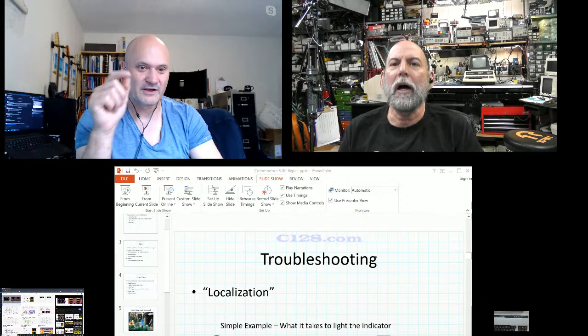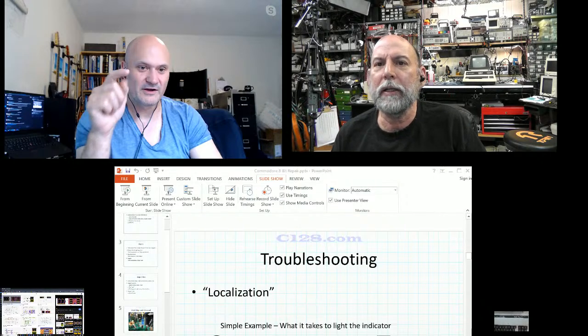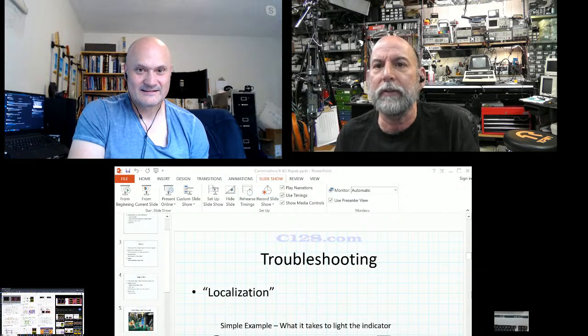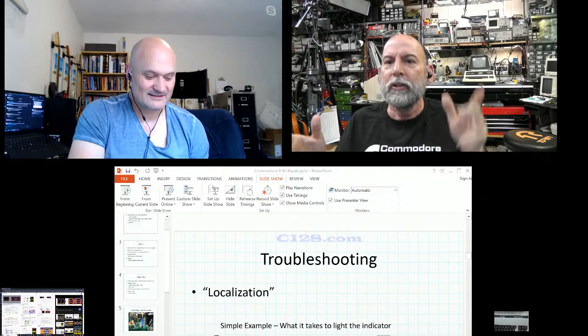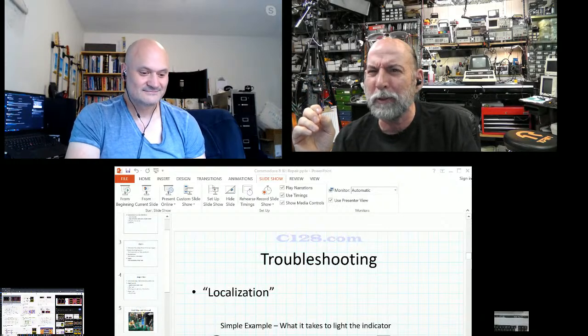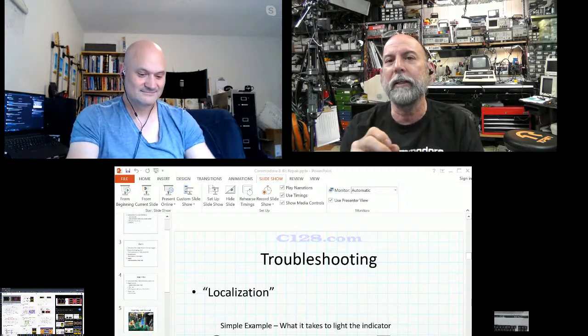So, Ben mentioned audio troubleshooting, and one thing I'll say about audio troubleshooting that was an advantage then is that there was a left and a right channel. One of the advantages to troubleshooting audio equipment, especially without schematics in the old days, was you had a left and a right channel. So a lot of times you had a known good channel to compare it to. So if you go in there and you say, well, that looks a little clipped, but is it clipped or not? Well, you would look at the working channel, and it oftentimes would give you an answer to that.